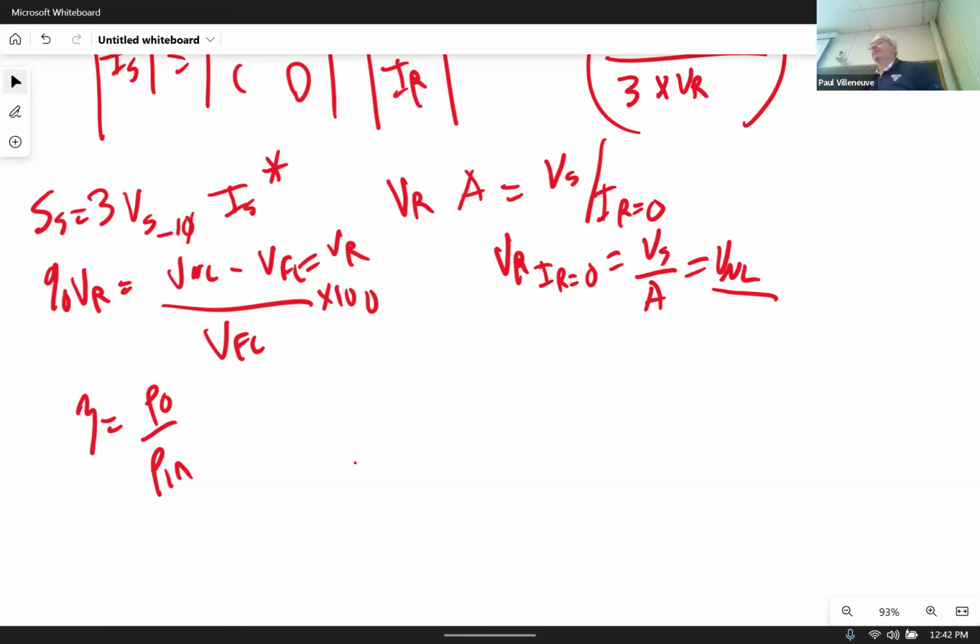Yes, sir. Is there a reason why it's not both on? What was the length of the line? 8 kilometers. It's right at the limit. And since you had all the ABCD parameters, all the values to calculate, you remember what I said in class? It's always better to be more accurate. So I would always just use the medium length lines if you can get them. The short line is going to be close, so we can ignore it, but if I have the parameters, it really isn't that much more work to calculate it. So calculate all 4.